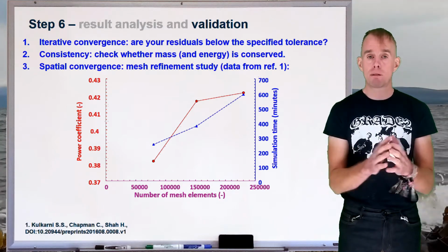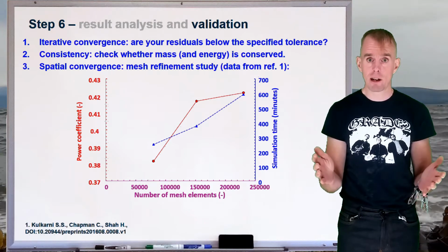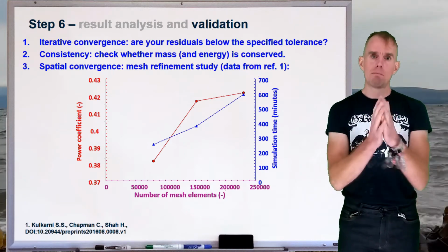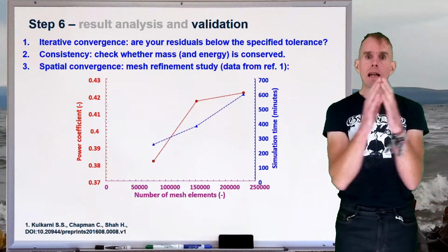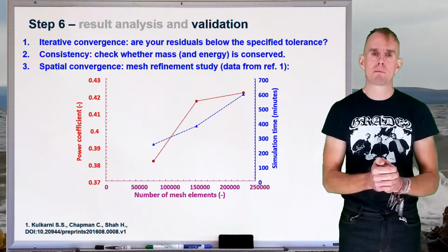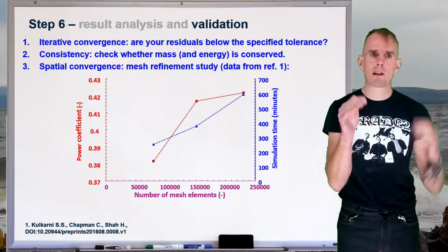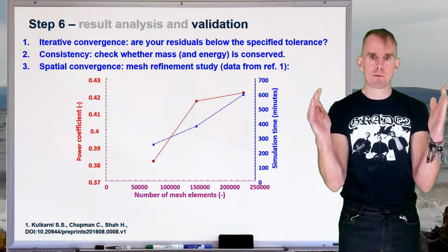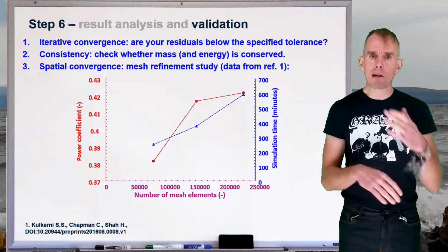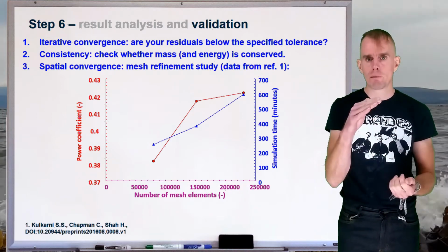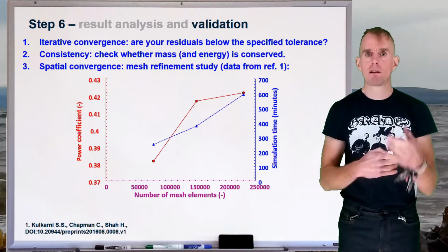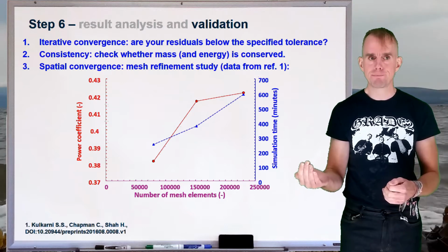It might be a pressure drop, for example, in a duct. It might be a velocity at a given critical point. It might be, for example, the length of a recirculation zone. If you imagine that backwards facing step problem where you have that recirculating vortex, it might be the length of the vortex. There will come a point where whichever parameter you've chosen will start to asymptote and flatten off and become largely independent of the mesh that you are using.